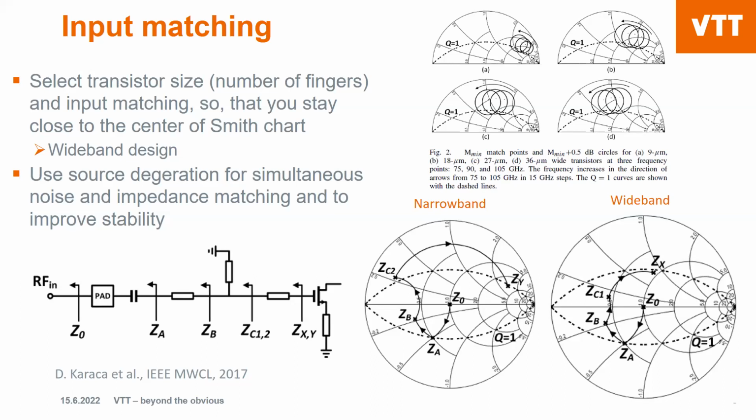Here we are not hitting the minimum; we are hitting inside the 1.15 times for this design, because we want to stay in the middle of the Smith chart. You can see Zopt in the schematic on the left-hand side, which wants to show that impedance to the gate of the transistor. So fairly straightforward.